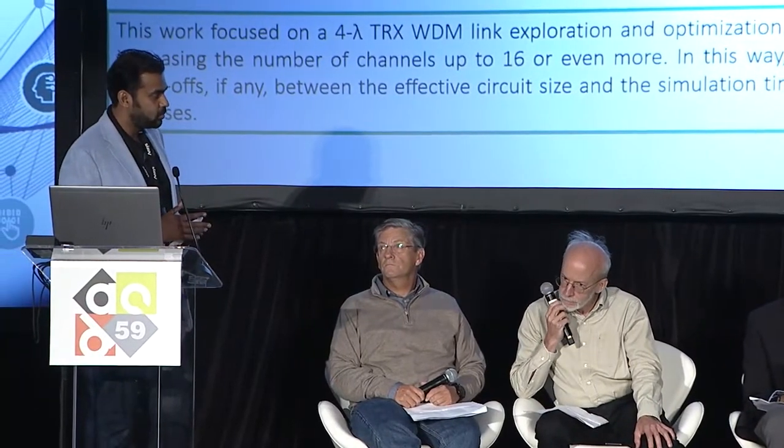I believe it's going to be a significant improvement because the first stage where you're setting up your circuit, you are doing that anyways. Even if you're doing manual tweaking, you will have to set up your circuit in a circuit simulator. And then the second and third step, from the designer point of view, it takes very small amount of effort because the tool has these wizards that you can launch and just pick your design parameters, pick the range over which you want to vary them for. And then the tool will automatically launch multiple simulations and change the parameters in an adaptive way. So it kind of runs the simulation, gets the responses, and decides how to change the parameters in what way.